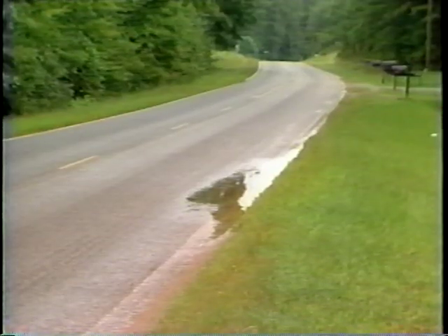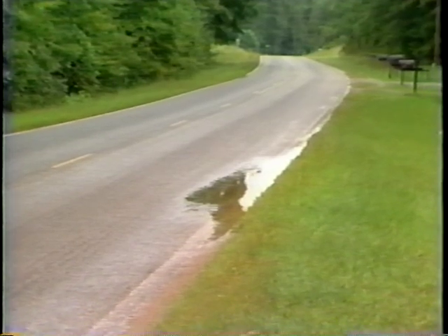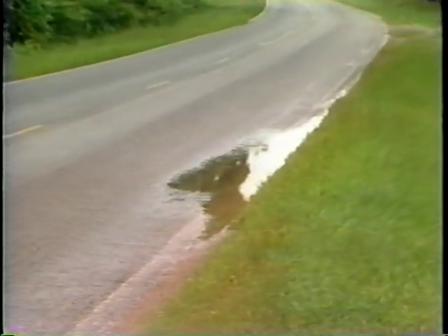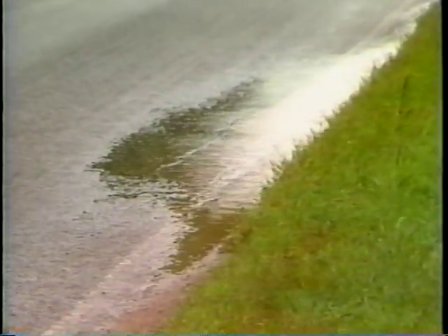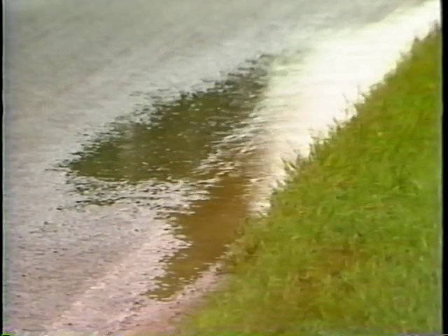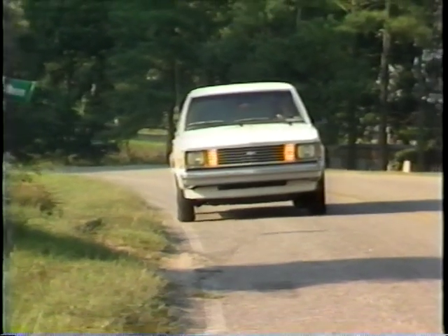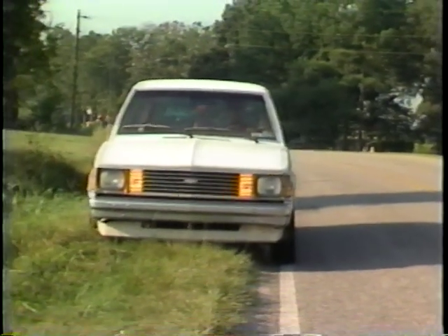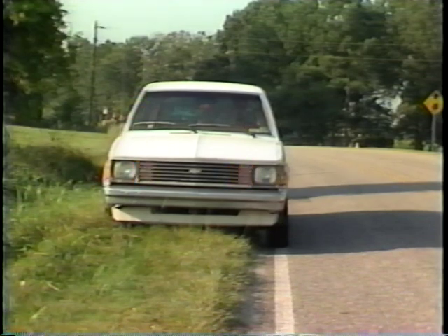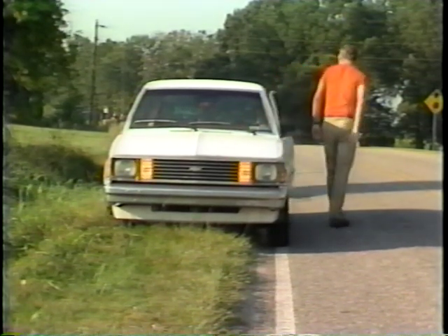Water standing on the edge of the pavement may filter through the roadway and down into the base and subgrade below. Vehicles running through the standing water can suffer a loss of traction because of hydroplaning. High shoulders may be a problem for a driver trying to make a smooth emergency stop on the shoulder, or perhaps trying to recover control of a vehicle in an emergency situation.